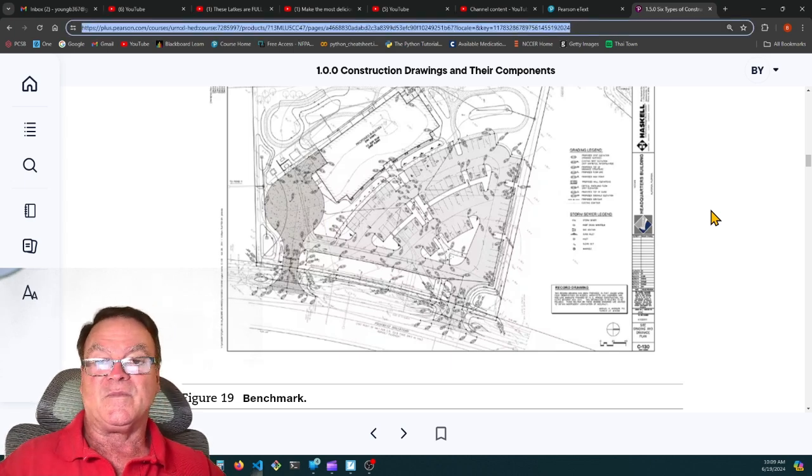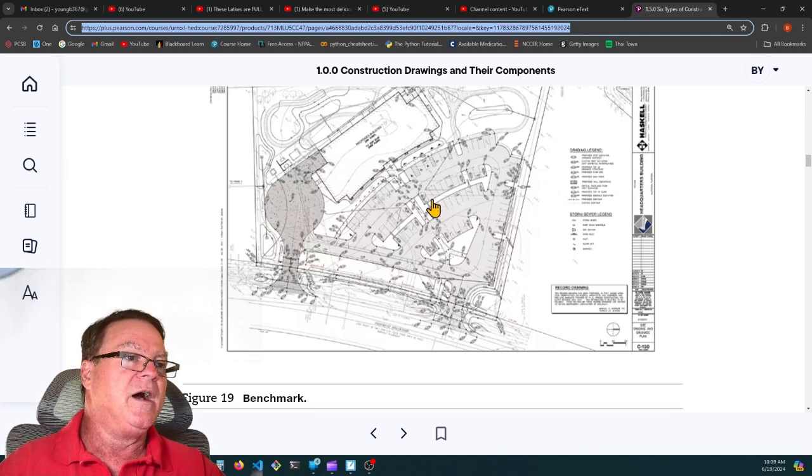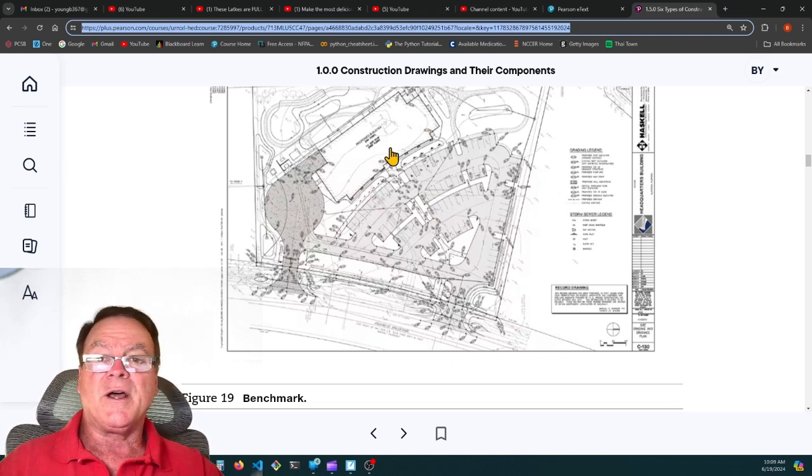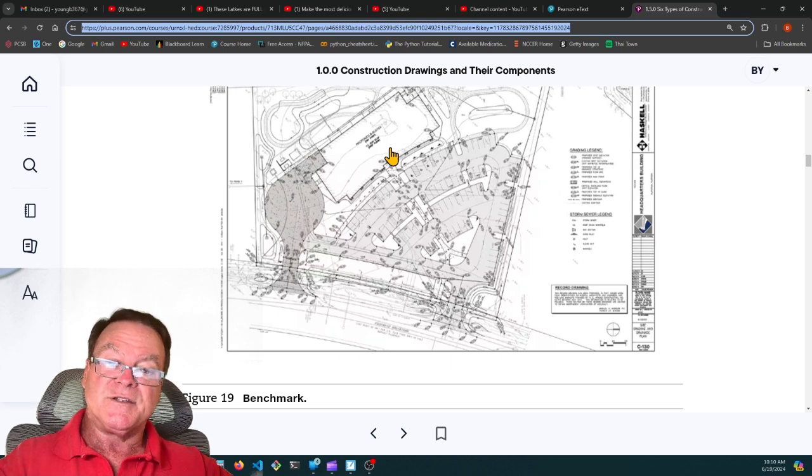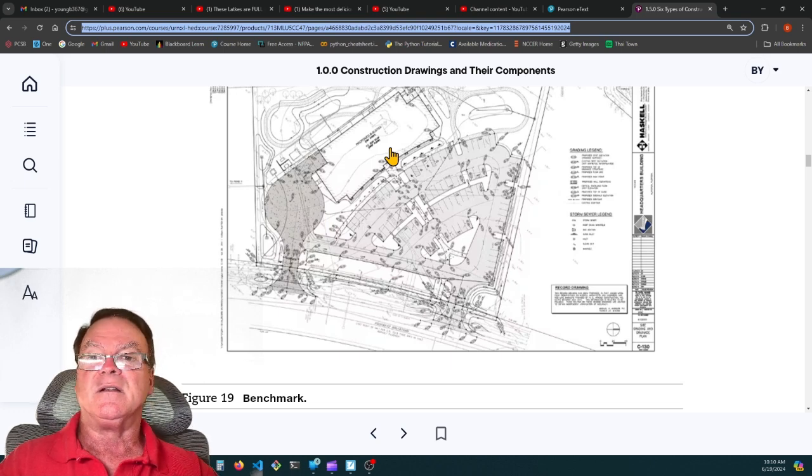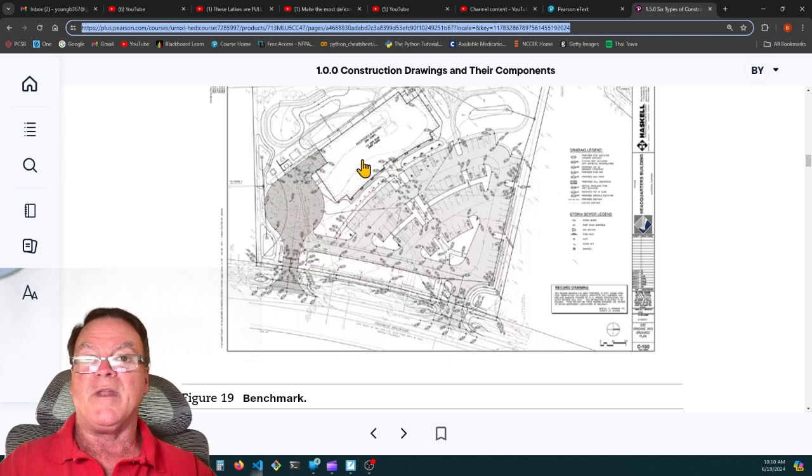And it's leaning to this day. Anyway, if they bring in a lot of dirt, they'll actually bring in much more dirt than they need. They'll bring in tons of earth and build up big mountains of dirt for the weight, so that it'll compact the dirt below it, and then they'll let it sit for a month or two. After that's done, they'll come in with trucks and take out all of the dirt they don't need, and the dirt that's left behind is nice and compact, so it's not going to settle, and the building will stay put where they put it.